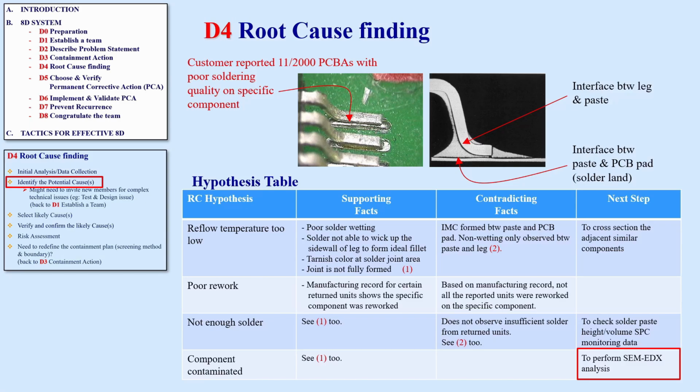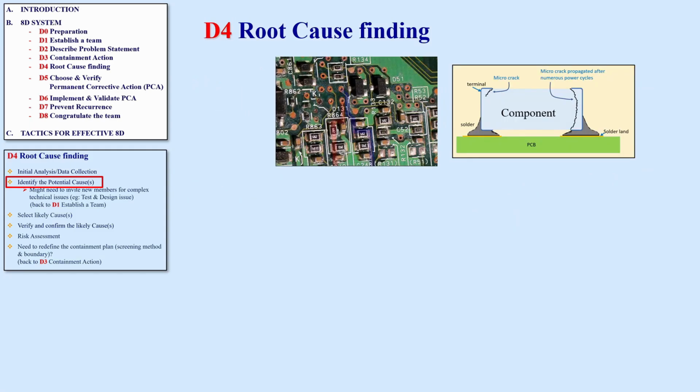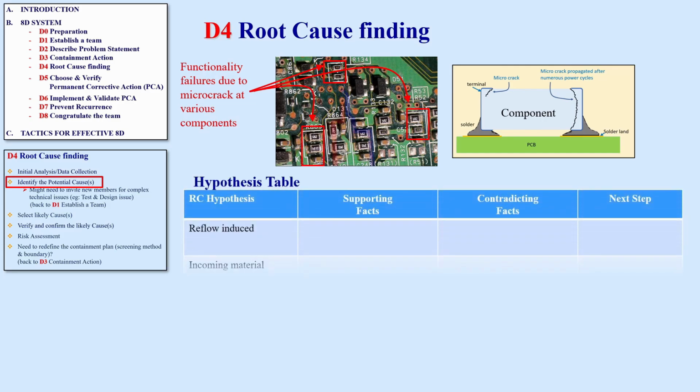To enhance your understanding of this critical tool, let's have another case study. This time, we observed functionality failures due to microcracks at various components. The potential root cause hypotheses are: reflow induced, that is, the temperature too high; incoming material; SMT machine induced; and customer induced.